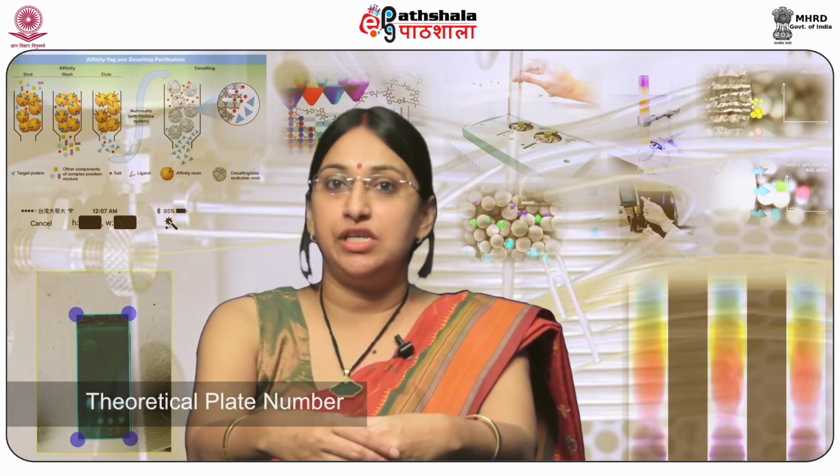Height equivalent to theoretical plate, HETP, is defined as the length of the column necessary for the attainment of compound distribution equilibrium. It is used to measure the efficiency of the column. If the length of the column is L, then HETP can be calculated as L divided by N. Theoretical plate number and HETP are widely used as a measure of resolution in gas liquid chromatography and in high